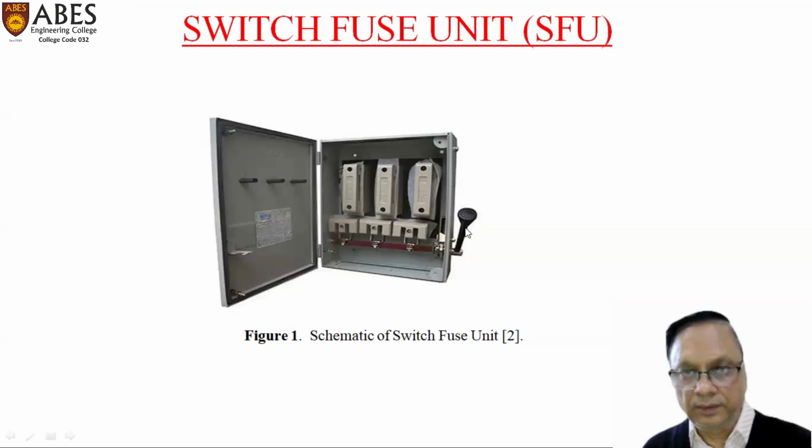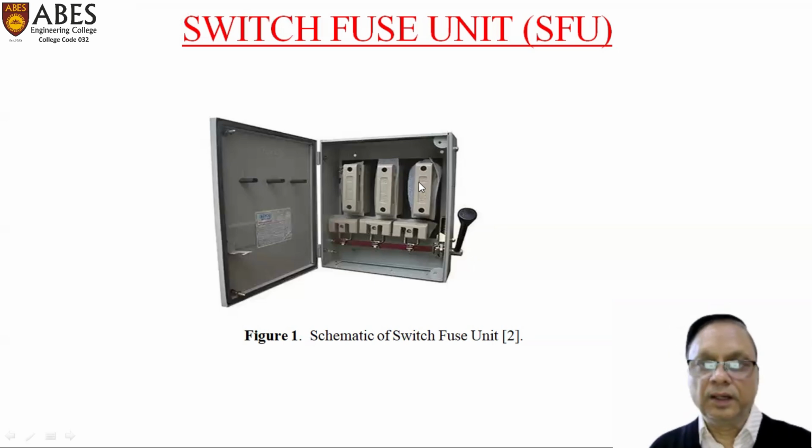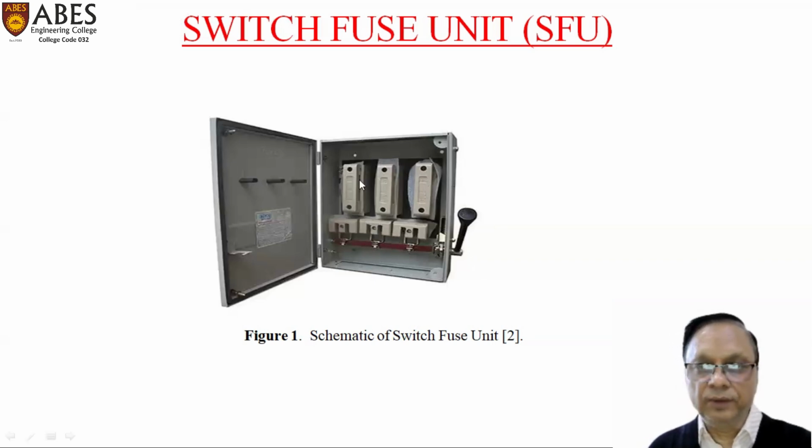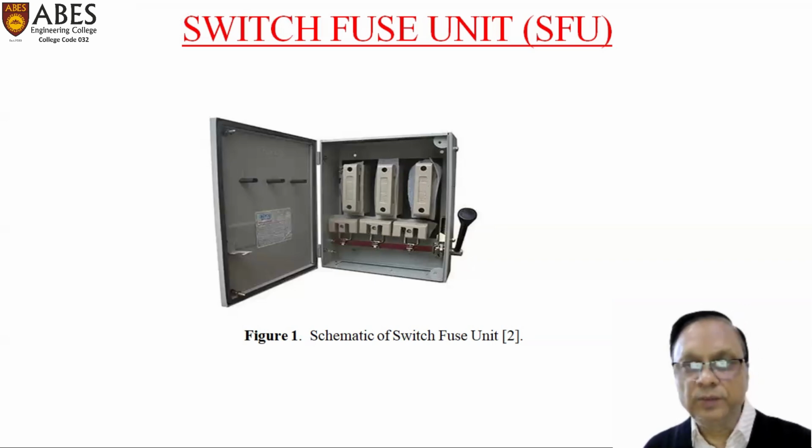This is manual. Whenever you have to give supply, we turn the switch handle in the upward direction. So the contacts come into contact, and then incoming and outgoing have a common connection. In case of any fault in any one of the fuses, the fuse is replaced here. So this is time consuming as far as replacement of the fuse is concerned.